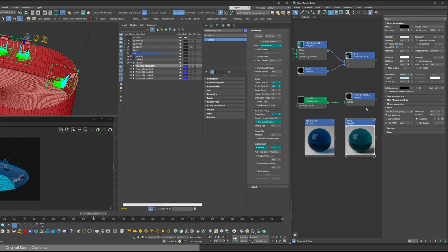Right, let me copy the fog color from the first one. It appears to have a slightly more green tint. The most significant change I've made is switching the affect shadow checkbox off. This is necessary if you want to enable the caustics. If you don't switch that off, even though the caustics rendering is enabled, they won't be calculated for this material.